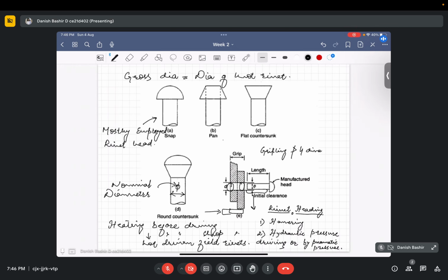The hot rivet becomes plastic, expands and fills the rivet hole completely in the process of forming a head at the other end. On cooling, the rivet shrinks both in length and diameter. Due to the shortening of the rivet, residual tension of an unpredictable amount develops in the shank and some compression in the plates to be connected. The compression causes friction to develop between the plates and is called clamping action.